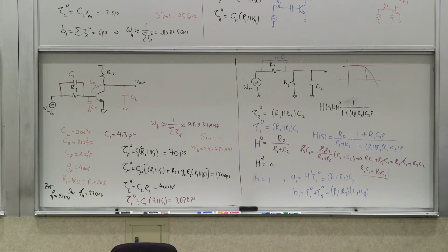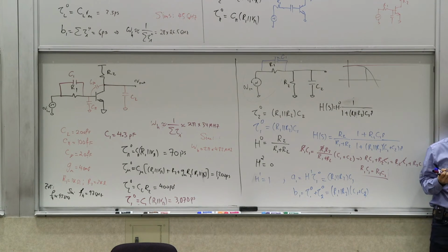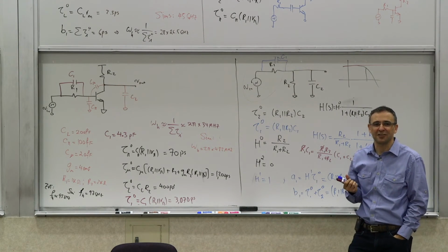So this can be used in several different ways. This is used a lot. Most likely you've used it already in the lab. If you've used an oscilloscope, you've used this. The oscilloscope probes, you've noticed that there's a 1x and 10x on them, right? Almost all of them. Why is there a 10x? Why do you want to have a 10x on an oscilloscope probe?